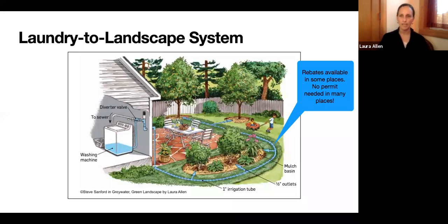One side of the valve goes back to the sewer or septic. When you've turned the handle one way, nothing has changed about your home. It's exactly the same. The other side of the valve now goes out to the new irrigation system that you have designed. So you're directing the water to your trees, your bushes, some of your larger plants. You're doing a match of how much Greywater you produce, how much irrigation need the plants have, and that's how you determine where to send that water.